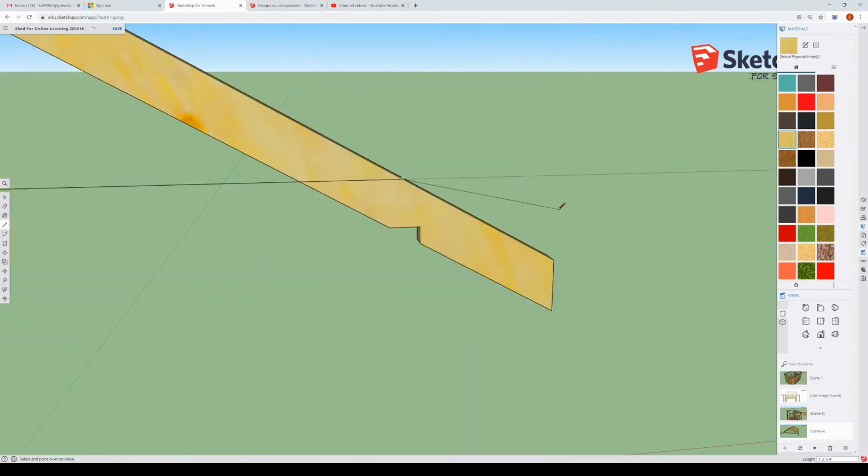And then I don't think we've really done so much of this yet, but if I hold my pencil right on that end point, and then I carefully move up, what's happening here is SketchUp is inferring that end point onto this edge. So I know that if I'm following straight up, and sometimes you lose your line for a second, but it's inferring to that edge so that I can go on the blue axis right down to that edge.